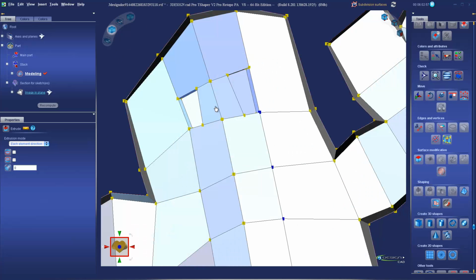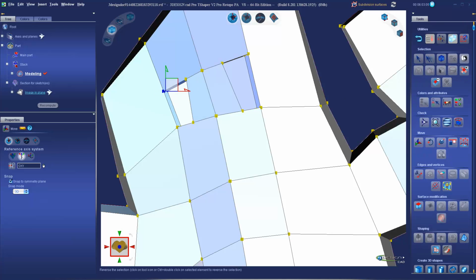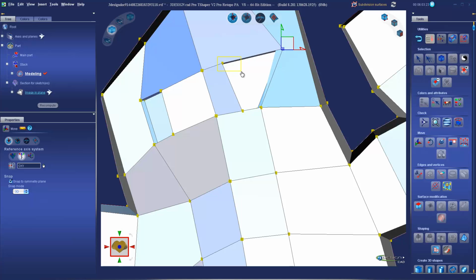And then in box mode, I'm going to move the points just to move these eyes over using the move tool. Grab those 2 points. I'm going to turn off back facing, so that if I want to select multiple points, I don't grab anything on the back side of the model. And just kind of change the location of these eyes to a more appropriate area. Do the same thing over here.